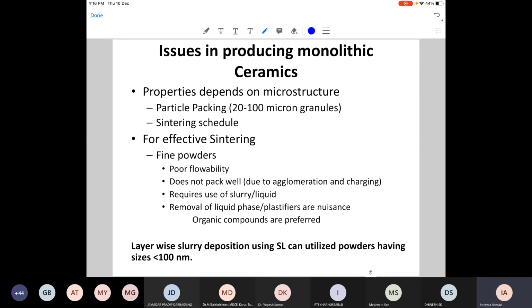That's one question. Now, design the sintering schedule, because the conventional sintering schedule may not work. In the case of conventional sintering, you use powders which do not have so much binder. Then you consolidate them by several methods, like isostatic pressing, or sometimes use hot press and other processes. But in complex shapes, you cannot use those things. You have to sinter it freestanding. And so whether the same sintering schedule is applicable there or not is another question, because you have a lot of binders.